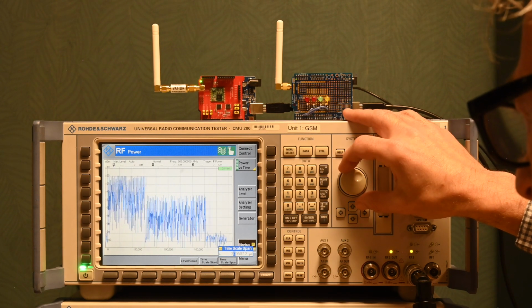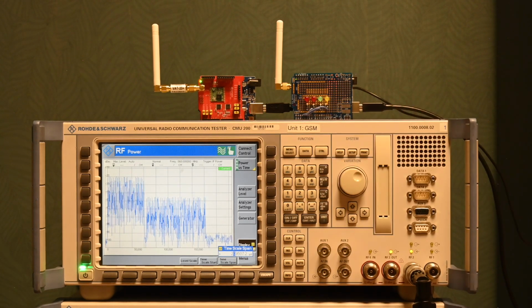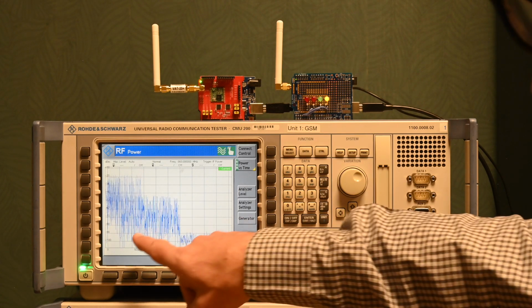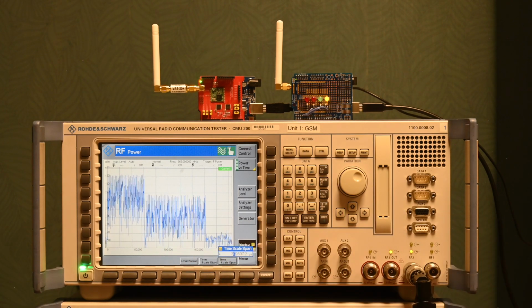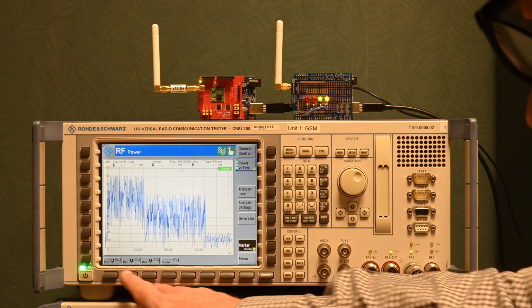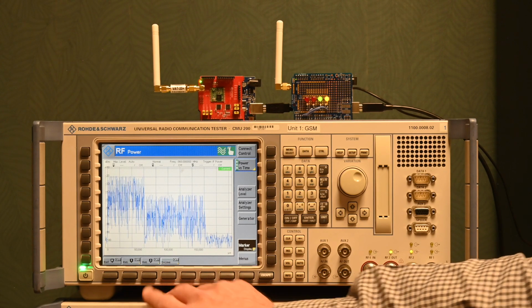Yeah, now we get the whole pulse even, but this doesn't make sense anymore. We got too much distortion. But if you're willing to live with some distortion, you can have a better idea and also make measurements about the length of certain bursts, using, for example, the possibilities that we got here with reference points and markers that we can put here.